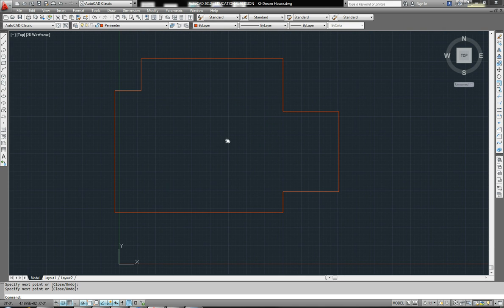From here, I need to give my walls some thickness. So very simply, I'm going to use the offset command and offset my walls in 4 inches. It's important to use the measurement of 4. It doesn't matter if your walls are 6 or 8 inches thick in real life. Just offset all your walls inwards 4 inches. It's important you stay consistent with the 4 inches, because the program that I use to generate the roof pattern has set to 4 inches as a standard.